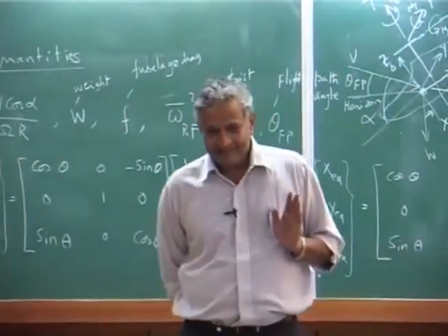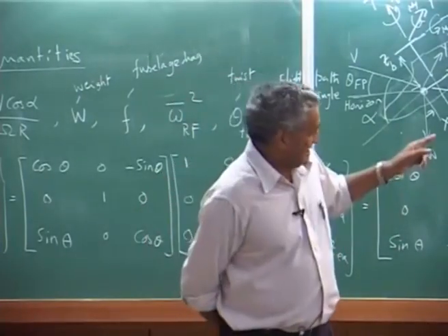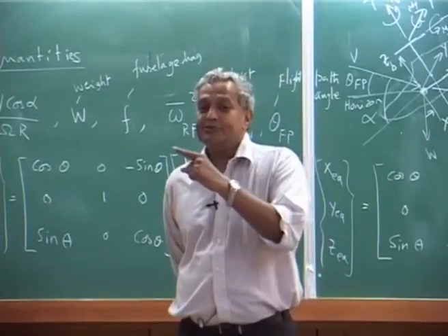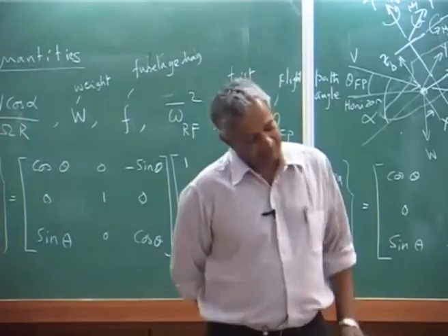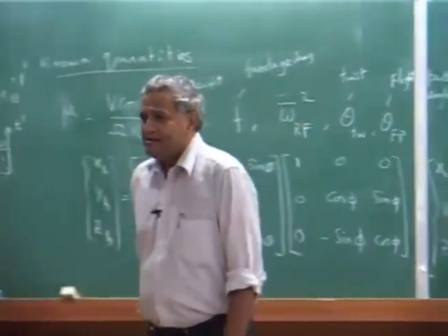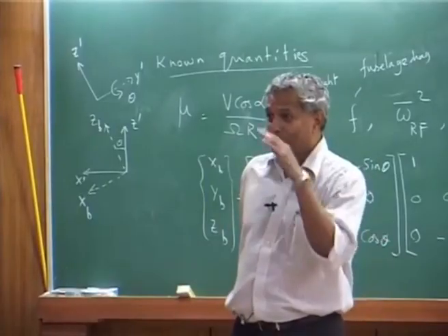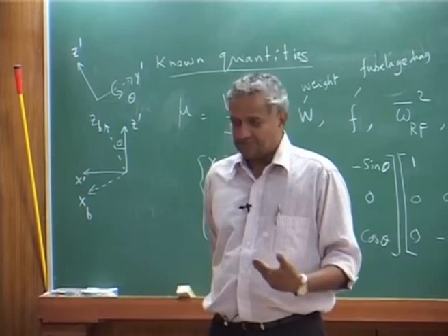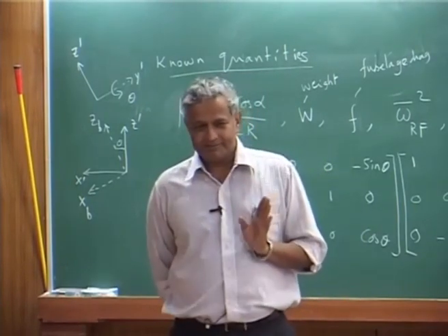The advantage they say is that I can use a component of the tail rotor force in the vertical direction. Is there a limit for the cant angle, or for changing the cant angle? No, you can't change it, it is fixed. It is an introduction in the design configuration, but not all helicopters have it.